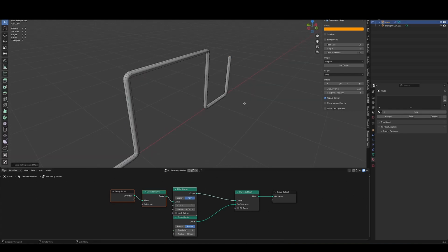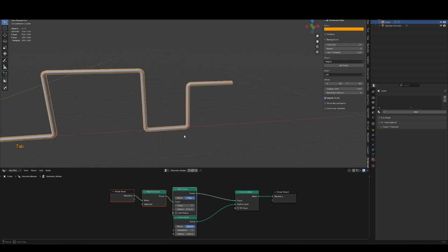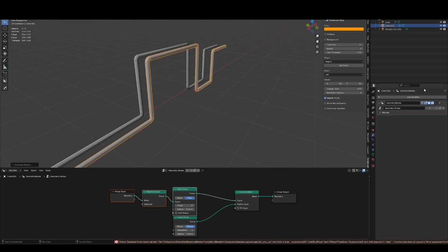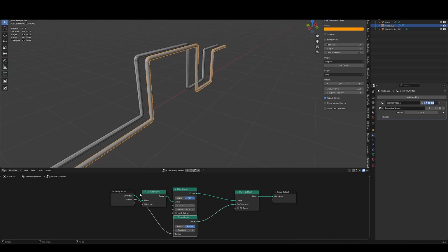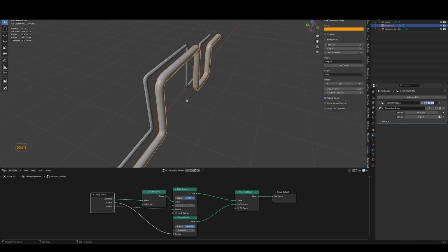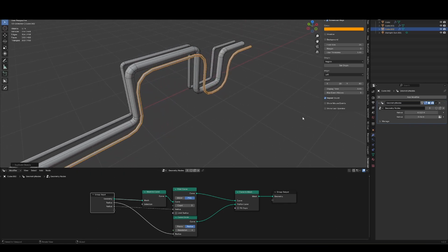And great, this is also our way to make a procedural pipe, where if I duplicate this, I can actually expose the radius value, and it'll show up in the geonodes modifier. And I can just tweak the radius, also tweak the fillet radius as well on a per object basis, as you can see. So this is leveraging, you can see by the number 3 here, it's leveraging the same geonode setup, but because I've dragged those values into the modifier here, I can tweak each individual one separately.